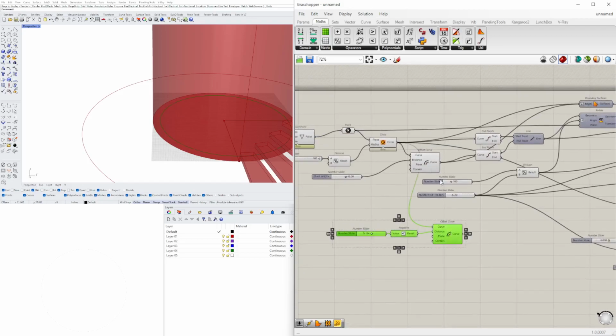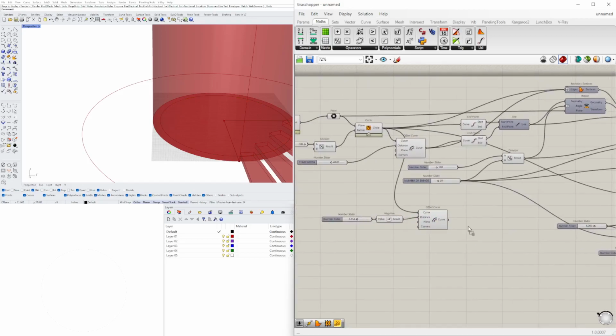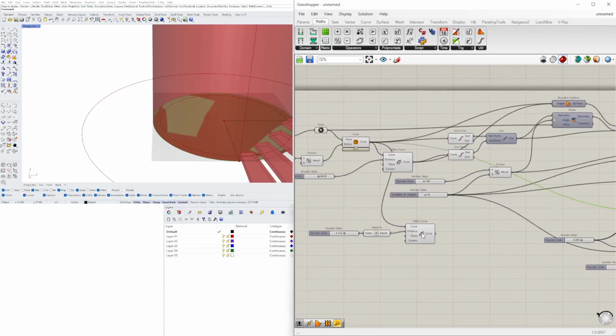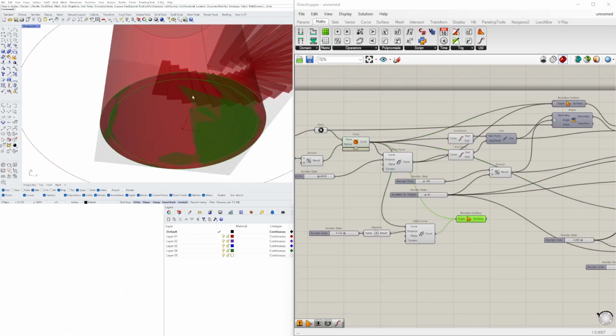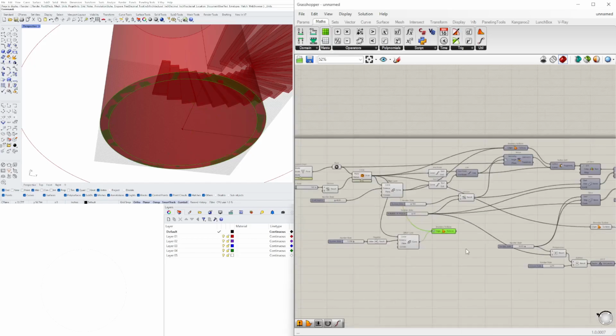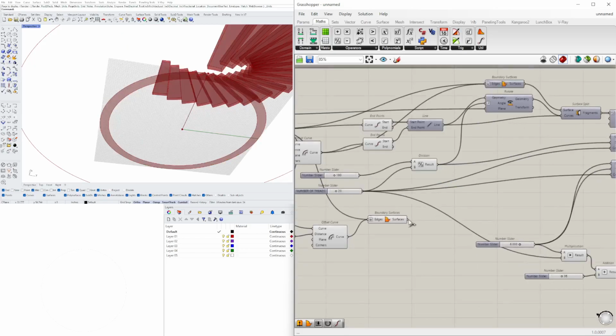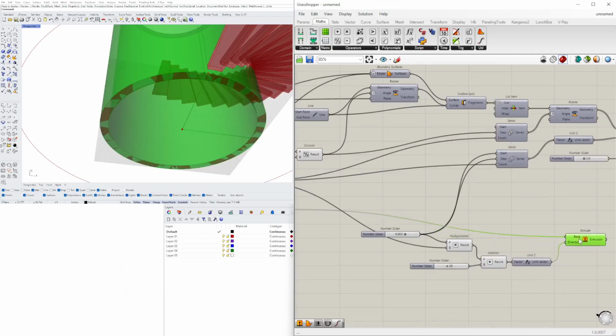And now when we take this, and actually, so we have this surface before. Well, we want to create the surface between these two. So I'll take this and create a boundary surface to override. So I'll plug this one, and holding down shift, I'll also add this input. Then, since they're overlapping, like I mentioned earlier, we need to flatten it so we only get that, and that is what we override. So we'll delete this and we'll use this to extrude it up.